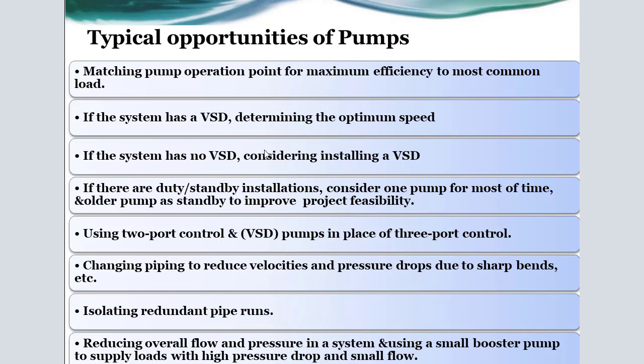If there are duty or standby installations, the energy auditor may advise considering one pump for working most of the time, and making the other pump a standby in order to improve the project viability in the building.